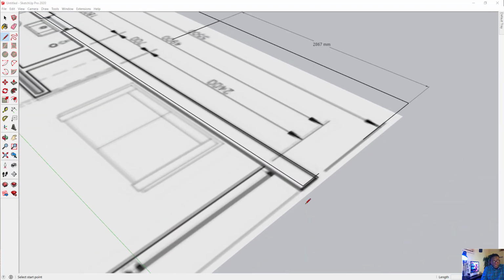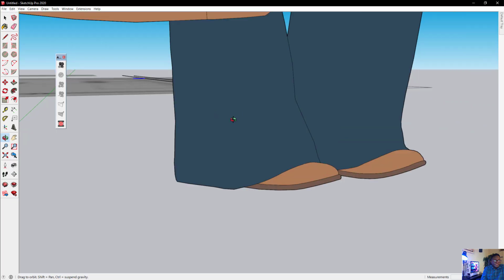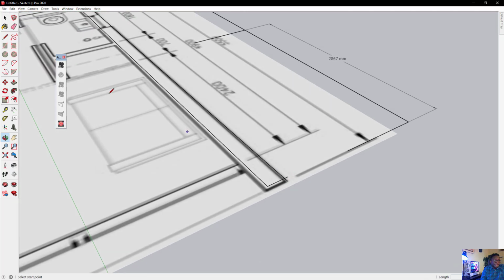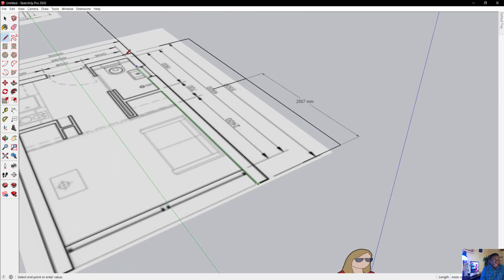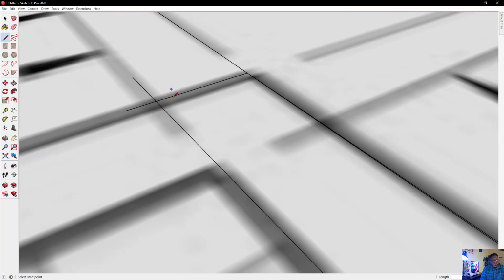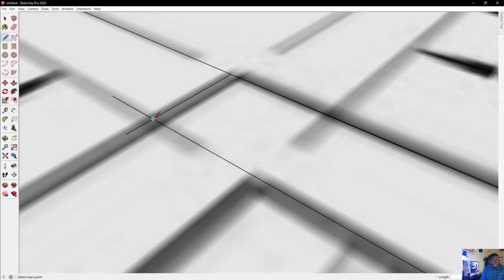And you know, when something is wrong, it's much easier to delete it and actually draw it over. So I'm going to start here and I'm going to go across here and type 200. Now I know that you might be saying, no way am I deleting a line and drawing it over, but in SketchUp it actually works out to be much easier to do that. Now notice I'm getting an intersection here, right? And if I use my eraser tool, it will actually erase these extended lines. So I can actually erase this here as well, and it will only leave me with those sections there.